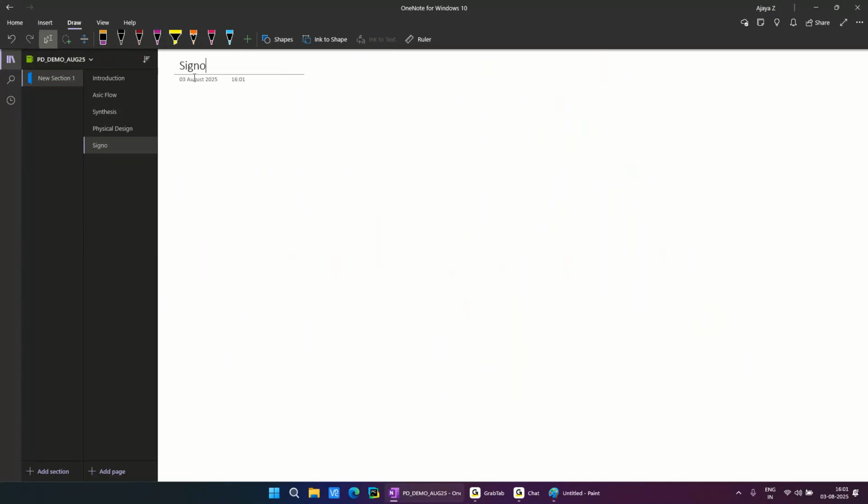Okay, so the next stage is sign off. In this sign off stage, you will have physical verification, STA, or let's say timing closure, functional verification, let's say in simple terms LEC, and next power. So like this, you will have multiple sign off checks.